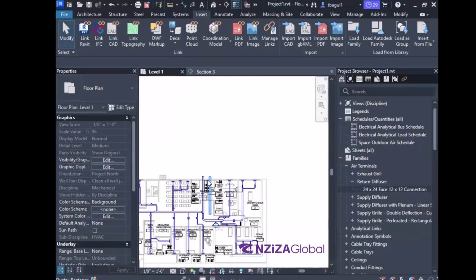Why are we trying to do that? We are trying to maintain that 21 to 24 degrees centigrade set point for the patient room. If you open a window and it has rained outside, the humidity has increased, and you're trying to open the window, that set point in that patient room will also increase, right? And that will differ from the standards.